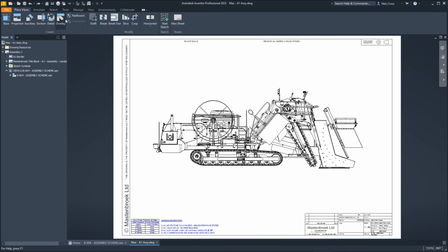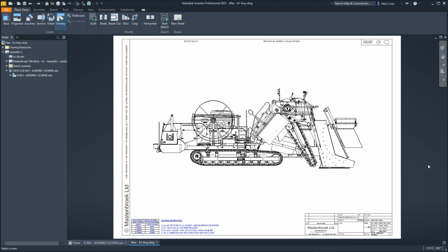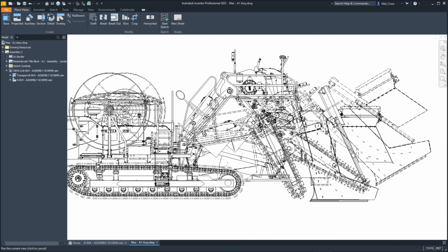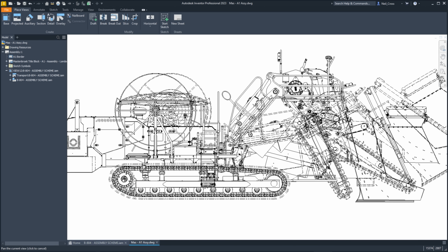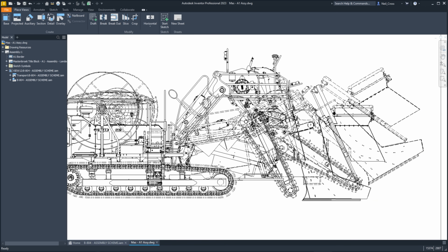One POSRep could be, I don't know, an assembly with an angle constraint set at 0 degrees. The next positional rep is the same assembly with the same angle constraint set at 90 degrees. But the end result is what that constraint change does to the actual model. It could represent real-world movement or real-world position change, and it saves those as positional representations.